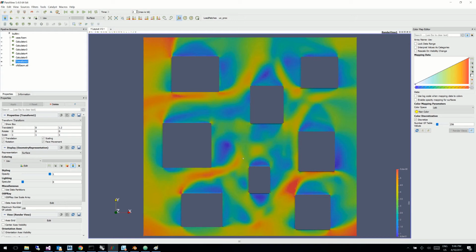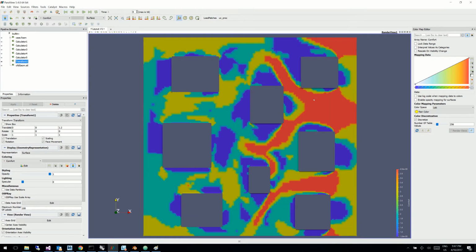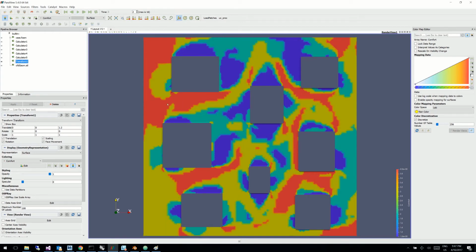So what's really cool about this is that we're aggregating the CFD results across either a full year or sections of a year, times of the year, and we're capturing the prevailing effects, which is really great. We can do all sorts of cool analyses with this. When you convert that back into a comfort map, you can see you get these prevailing effects. So in the summer mornings you can see that these areas might be exceeding criteria for walking. In the middle of the day you get it going every which way, and in the afternoon you also get a strong westerly prevailing pattern, and you get some wind tunneling and areas which are exceeding walking criteria here.